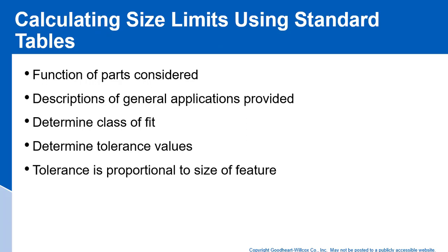Calculating these size limits, that's what I said we're not going to be doing in this class. We're just talking about this. But you need to consider the functions of the parts being considered, to select what fit you need. And the descriptions of the general applications are provided. Then you need to determine the class of fits and determine what the tolerance values are.